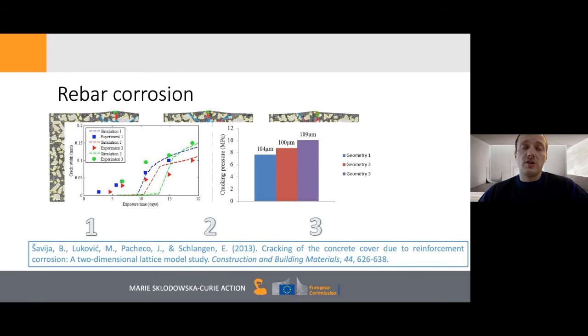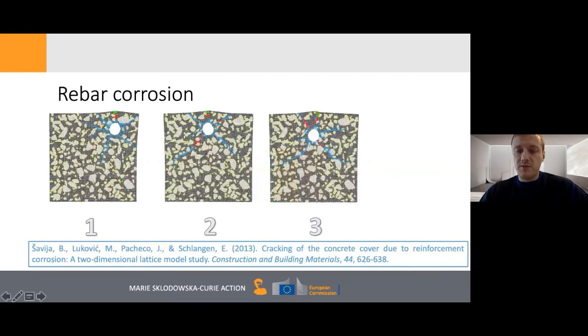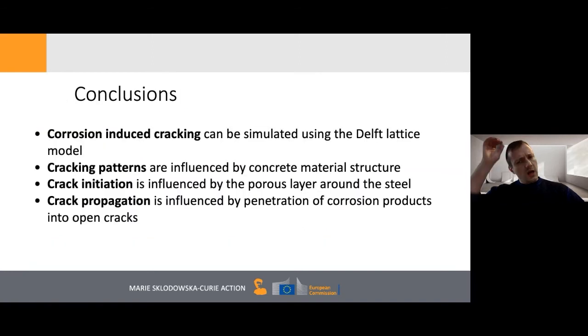So how much steel has been corroded at that moment. So actually, this geometry needs more corrosion before it shows cracking compared to this geometry. This is a bit expected, but it also means that we need to be very careful with assessing what is acceptable. If we accept higher levels of corrosion, in this case, we already have damage. So be careful what we do in practice.